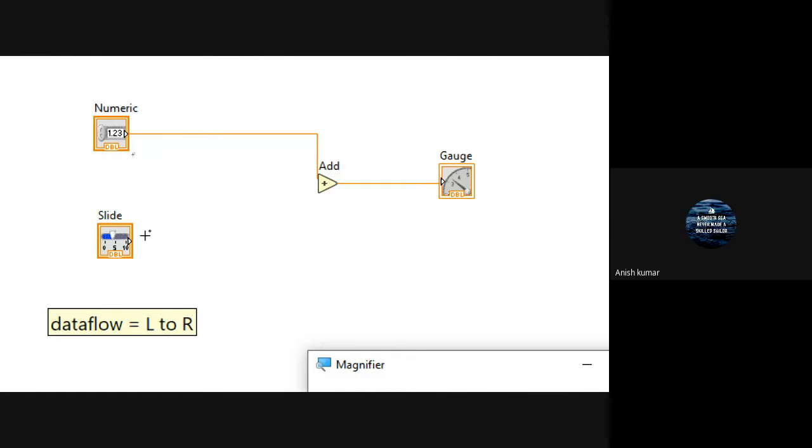So now it is plus, and as I go to this arrow mark, it changes to a bundle, and this is the wiring tool. Left click, drag, and as I move here it starts blinking. So it will start to blink, it means it is ready to accept it. So just drop it. Drag and drop. So you can move the wire anywhere, so you can play with this.